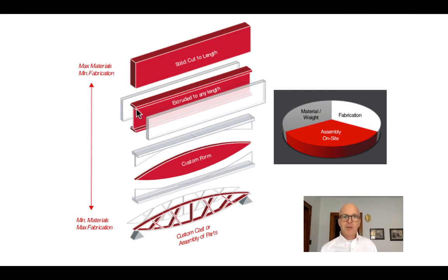And remember the logic behind an I-beam or a W shape is that we're putting most of the beam's material at the top and bottom in what we call the flanges. That's where the beam is going to work the hardest, basically, to resist the combined tension and compression that comes with bending. So a W shape is already kind of hacked.